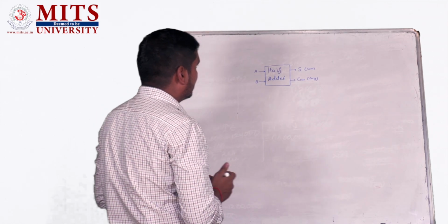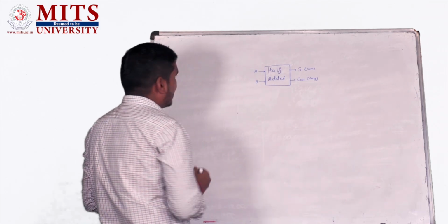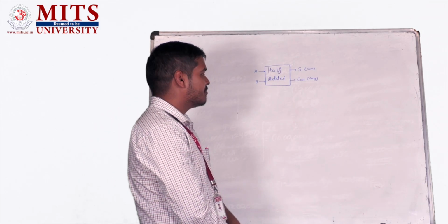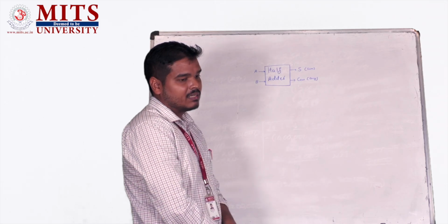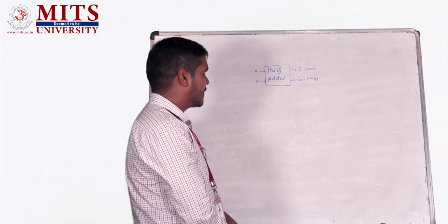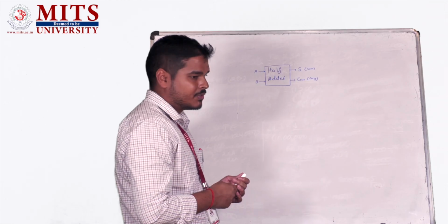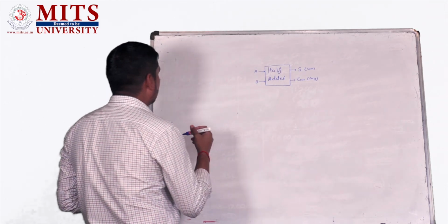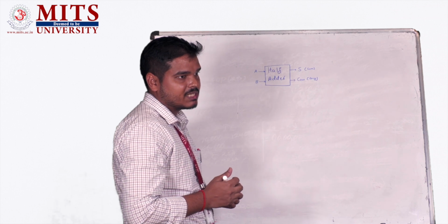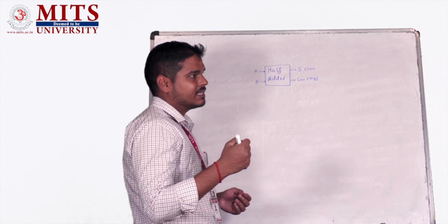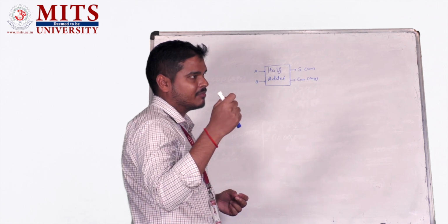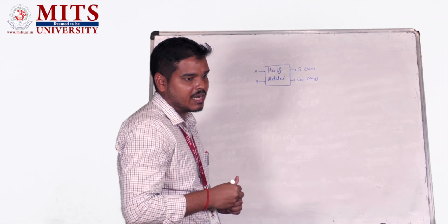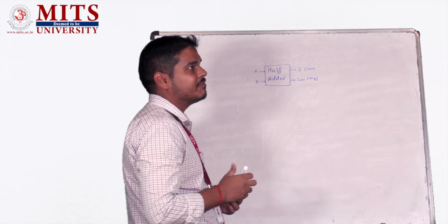So this half adder can be used only to add single bit binary numbers. There is no provision to add the third number or the incoming carry. So for LSB operation, suppose we have to add two 4-bit binary numbers, then for LSB this half adder can be connected, and later for the remaining bits we will be requiring full adders, because for remaining bits the carry may generate.